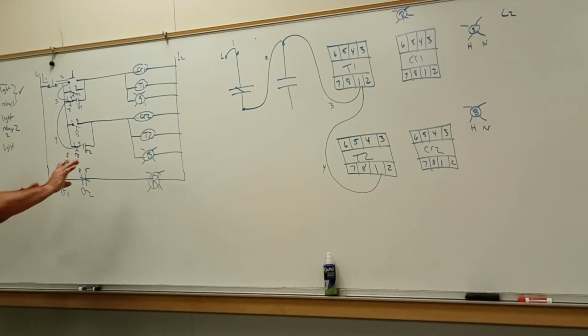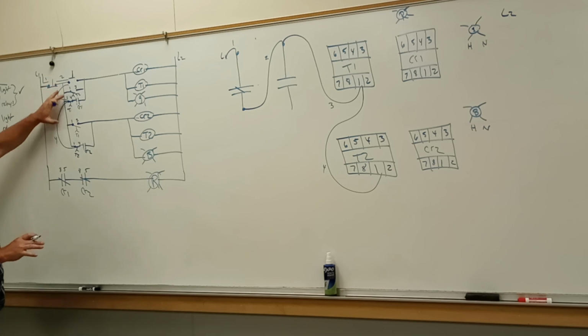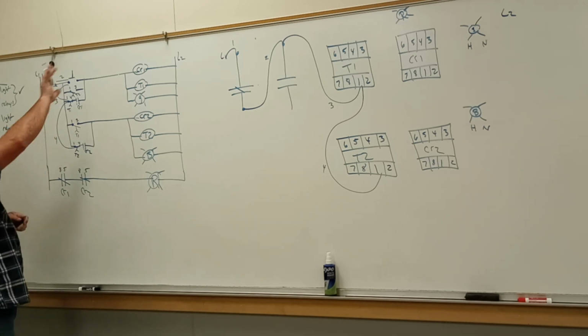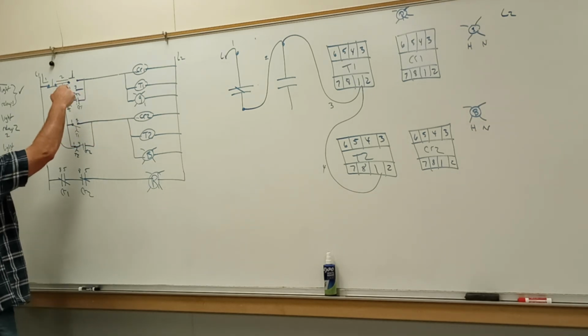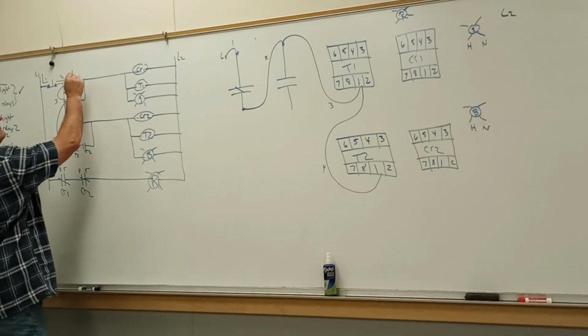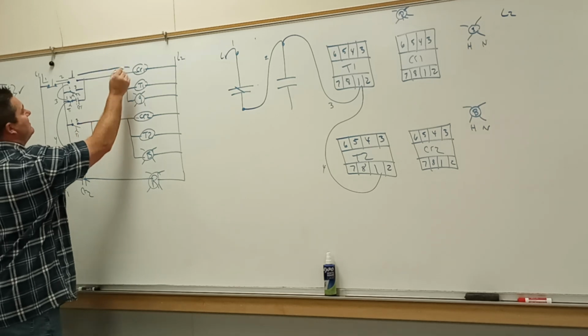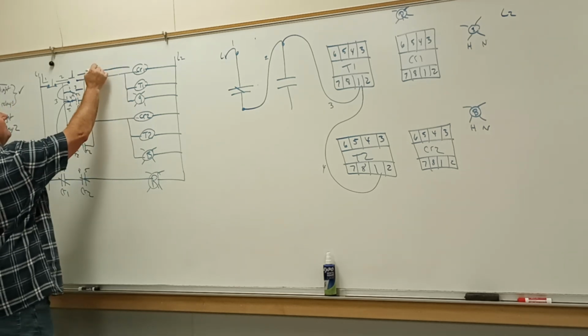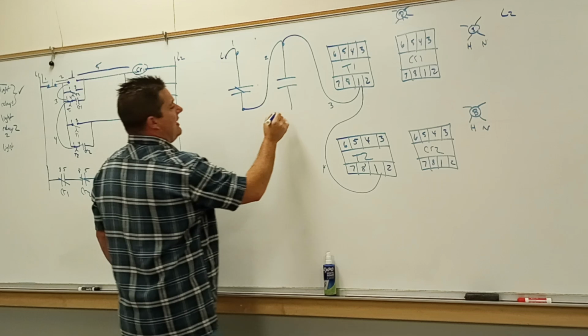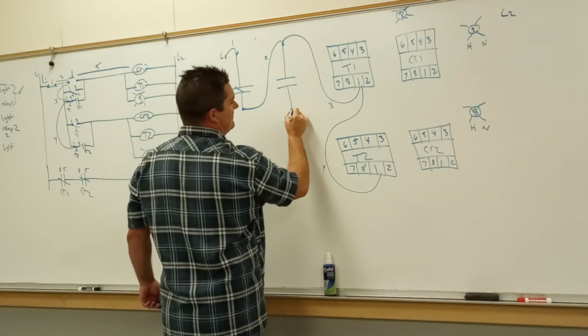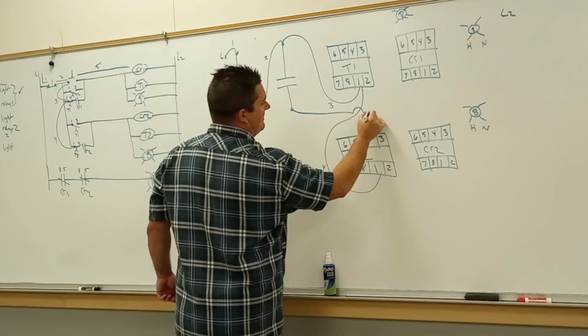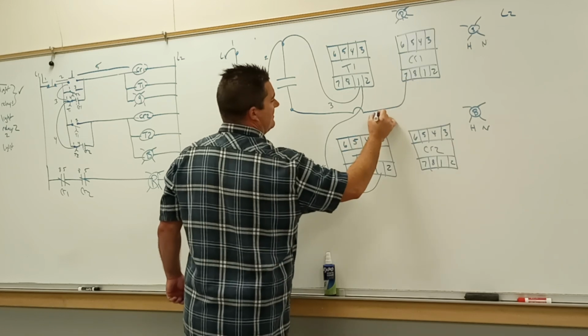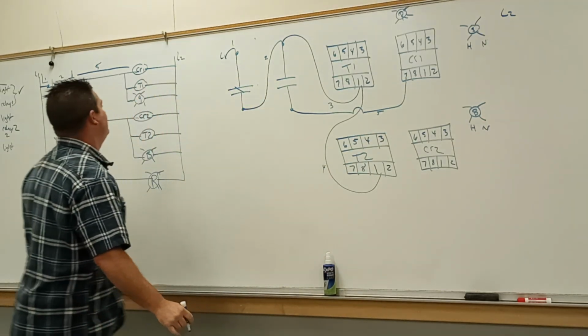So now that I've got that part of it set up, because I'm not duplicating all of these ones going down, now I start on this side of everything. So the out of my start fires my control relay, wire number 5. Out of my start, and when I make this little hop, it's just a hop over. So that's wire number 5.